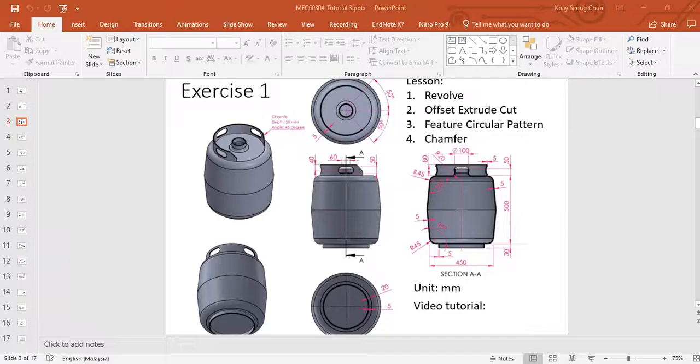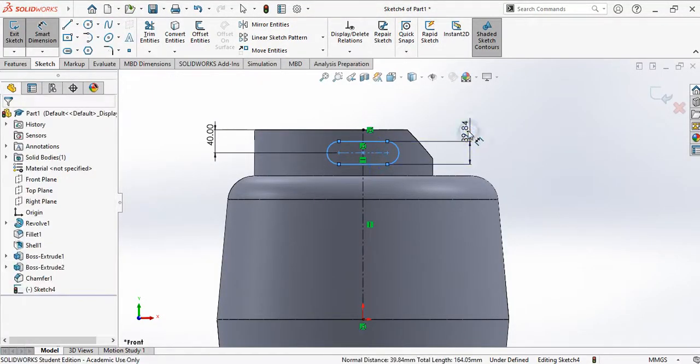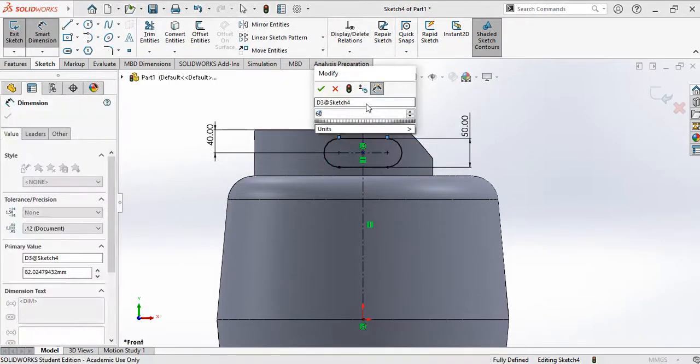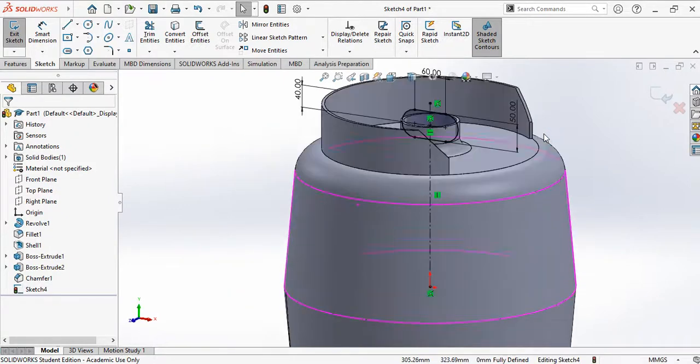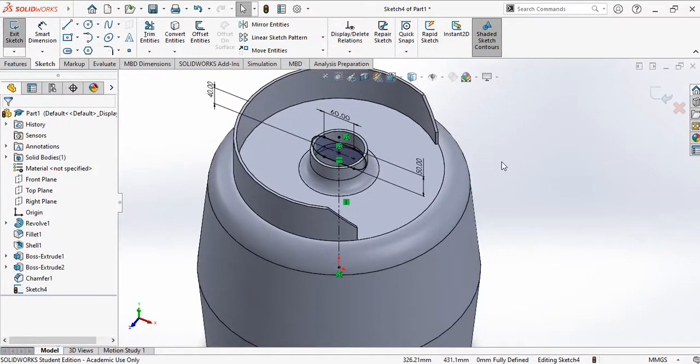And just now we checked the width is 50, the length is 60, so we will put here 50, and here length is 60. Okay, now I will click somewhere in the space here and use the arrow keys on your keyboard to check. Okay, seeing your mid plane at the middle, so your sketch will stay at the middle. So now we're going to have an extruded cut.